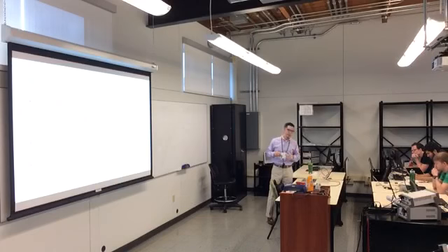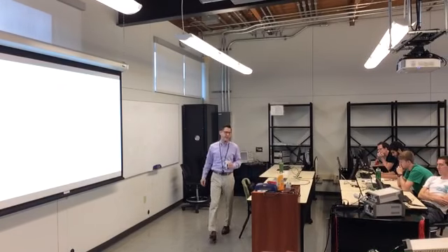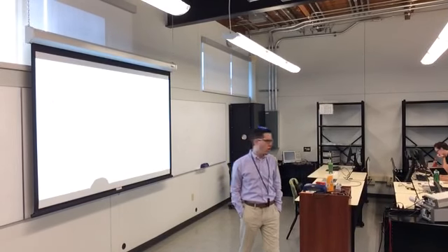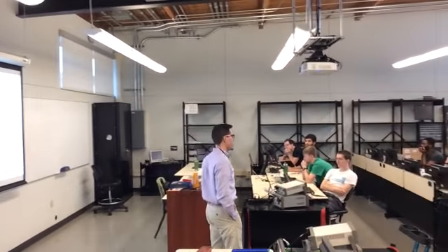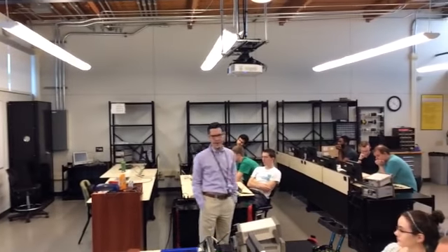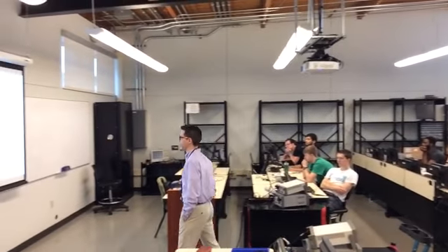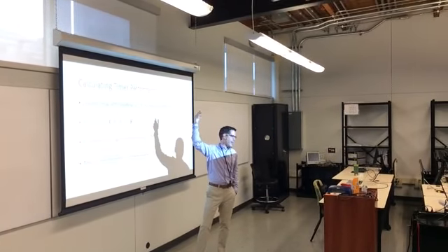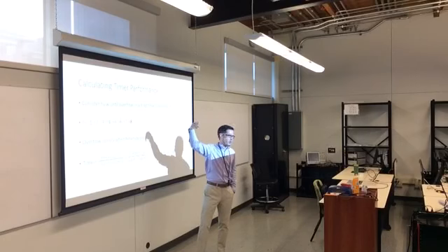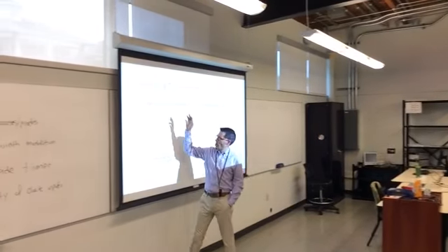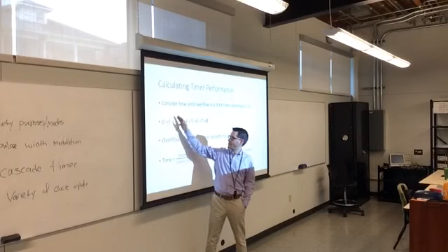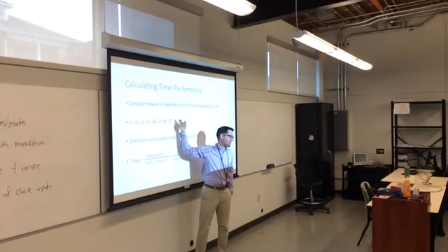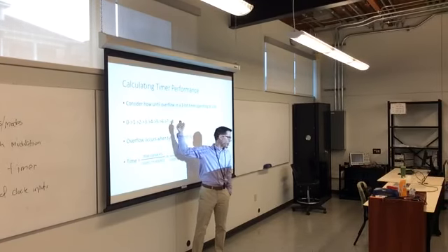So think about it this way. You've got a 16-bit counter. You've got a 16-bit timer. How long can you use that to time? And it's based on a variety of different factors. As an easy example, let's say that you have a 3-bit counter that's getting incremented at 8 hertz. So 3 bits means I can hold 0 to 7. And so if I go 1 second, 2 seconds, 3 seconds, on and on, I will overflow once I hit this value here. So once I make this transition, I will overflow.